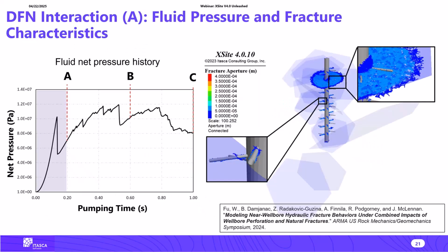So this example was done in the model where we assume that the rock mass is massive and homogeneous without any pre-existing joints. There is another similar example in which we assumed that there are pre-existing joints and studied the effect of this DFN on fracture initiation. Those pre-existing joints in the near wellbore environment are shown as these transparent polygonal surfaces. On the left, we show the simulated injection pressure at early times. And on the right, we show the geometry of the induced fractures at these different states.